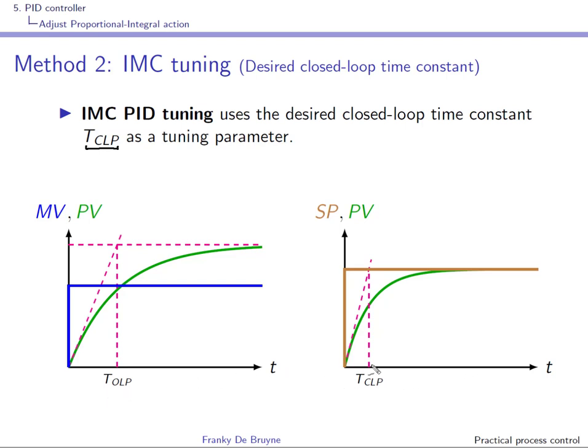Of course, you can also do a step, but in closed loop, and therefore the algorithm is active. The PI or PID algorithm is active, and therefore you have to do the step change, here in brown, really on the set point. Here it was done on MV, right? And of course here PV, if you have integral action in your controller, should go to set point.